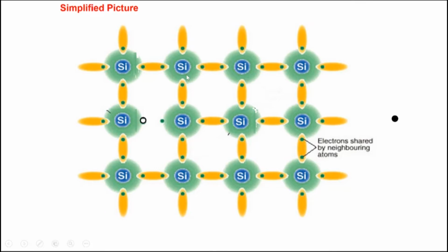Now, these phenomena are complicated. They require quantum mechanics to explain them in detail, and therefore we are painting a very simple picture. But the basic concept is that because the silicon atoms are not in their place, they're vibrating. As a result of these vibrations, the electrons get scattered. They move a certain distance and then they get scattered. Then they move a certain distance, then they get scattered. So electrons are executing some kind of a random motion, as I've drawn here inside the crystal.